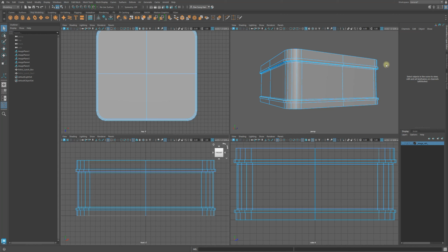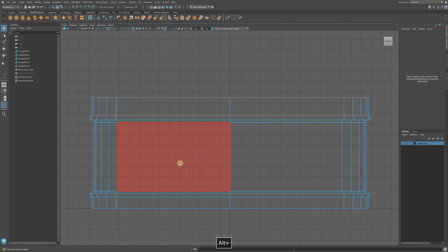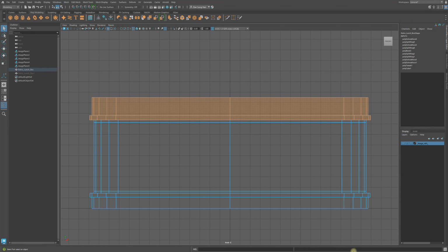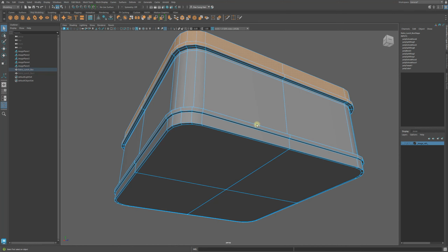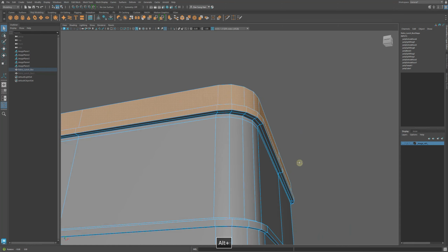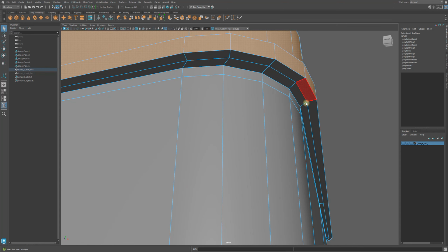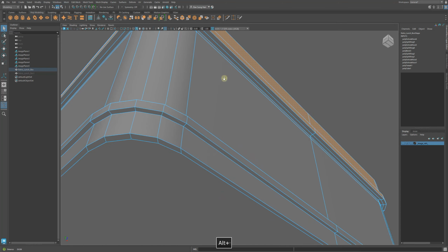And I want to detach the lid. Spacebar, front. From the outside, I'm going to marquee drag and only select up to here. All right, up to here. Let go now. Spacebar, spacebar. Let me see what I did. And it looks like I got almost everything, except for down here. See that? I need that, because I want to detach that chunk, including that lip.